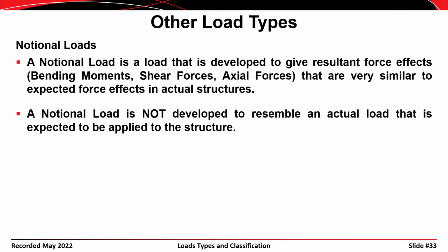Another case would be when a building is constructed or designed, you have to consider the fact that the building might not actually be erected in a perfectly plumb situation. It might not be perfectly vertical. It might have some initial out of plumbness. In order to consider that explicitly, that would be very challenging.